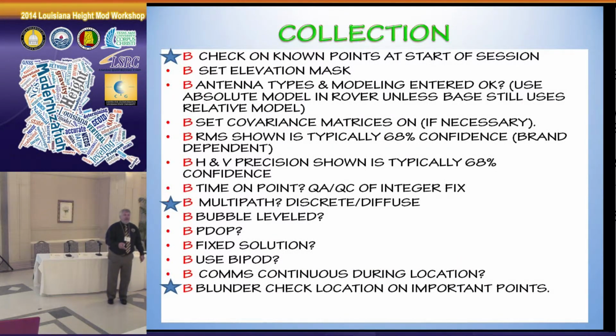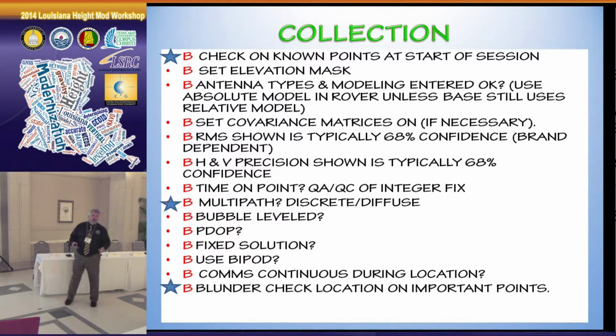Always check a point at the beginning of your session for real-time positioning. I don't care whether you're using a network or your own base station. There are too many ways to make blunders, especially with your own base station, than I can think of. And you want to make sure that you check just to be sure. I don't care if it's a topo point, something you did yesterday, whatever you got, the best thing you have. Go out and check it. And then you go. Make sure you check a point.